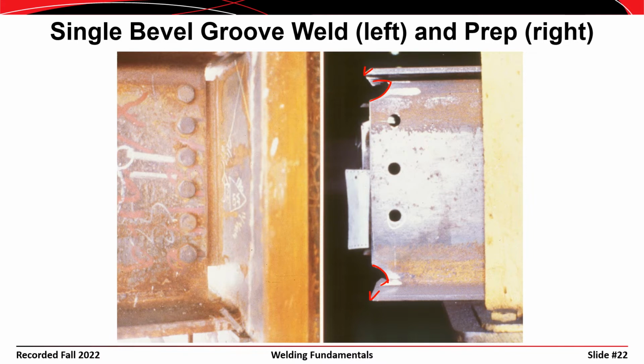And then this is a similar beam on the left where the beam has been bolted into place. This is a backing bar here on the bottom and a runoff tab shown here, and we'll discuss those later on during the presentation, but basically they're in place to contain the weld metal and to allow the welder to weld continuously off the edge of the beam flange so that they can have a high quality weld even near the edge of the beam flange.